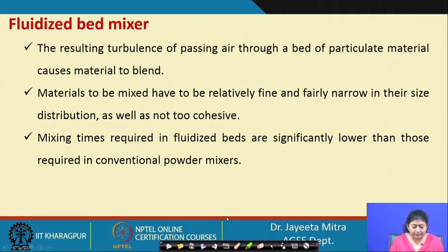Mixing times required in a fluidized bed are significantly lower than those required in conventional powder mixtures. This is because when we use the fluidized bed, each and every particle is in a fluidized state, and from all faces it is open to mix with the other composition, but that cannot happen when we use a conventional powder mixture, tumbling type, like that.